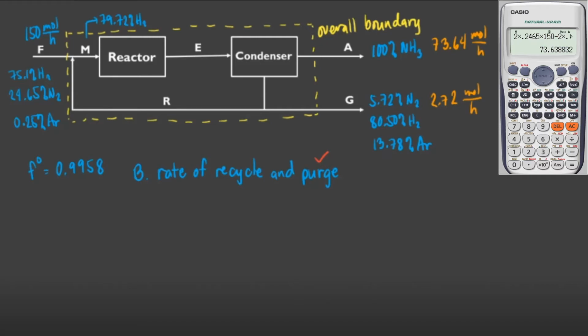My point is, we will be able to get the flow rate of the recycle stream if we perform the balance on the mixing point instead of the splitting point. So let's perform the balance at the mixing point. Keep in mind that the mixing point is a physical process. It's just a mixing process. Therefore, there is no chemical reaction involved in the mixing point. In this case, we can use the OMB, but we will have to rename it as the overall mole balance.